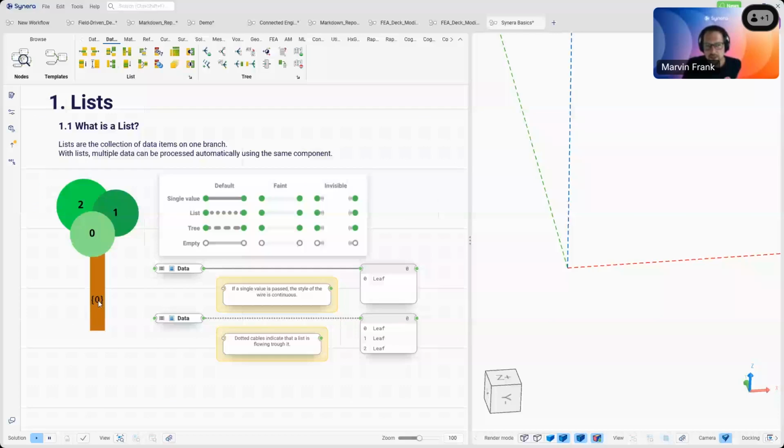So we always start the items with 0. Here you see that is the root 0, so this one root here. If it's a single list or single item, there is always only one root, and here only one item that is called leaf, and it's under item 0. So when we have a list of data, here still the root is 0, but then we have multiple data, and they are on the item 0, 1, and 2. So that's how the data is now managed.